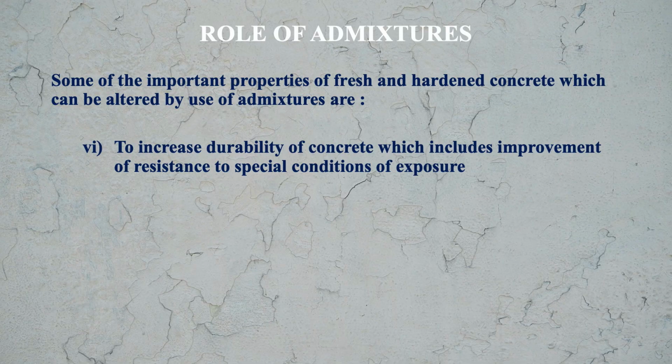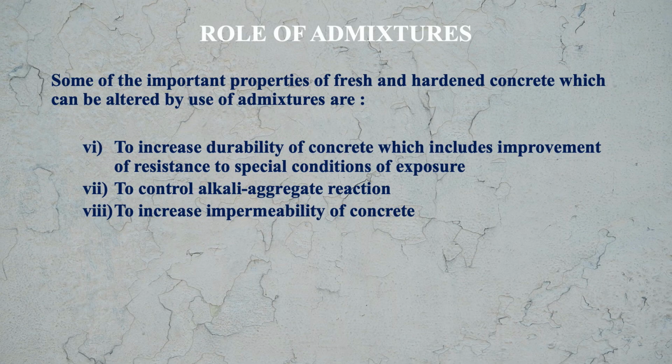Next is durability. We use admixtures to increase durability of concrete, which includes improvement of resistance to special conditions of exposure to the environment. Also, we want to control the alkali aggregate reaction by adding admixtures. As far as the impermeability of the concrete is concerned, we add admixtures to increase the impermeability of the concrete.